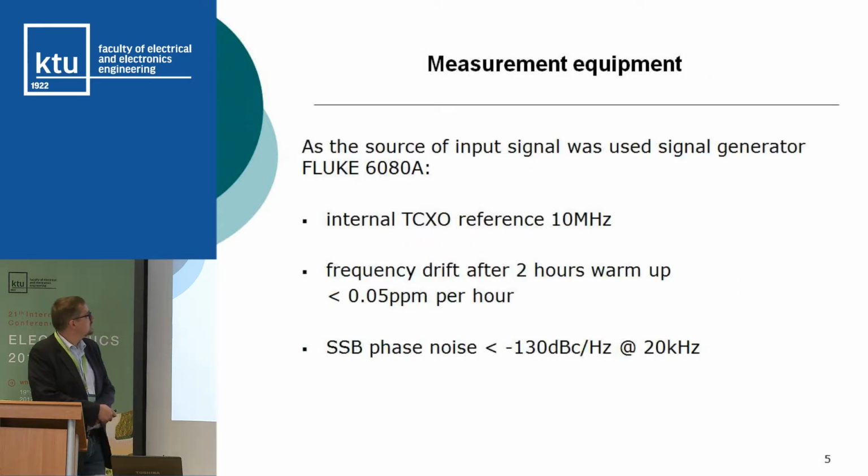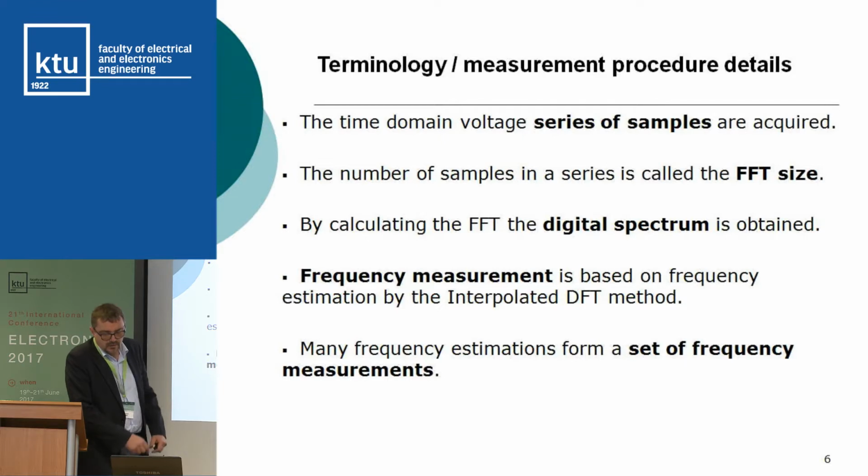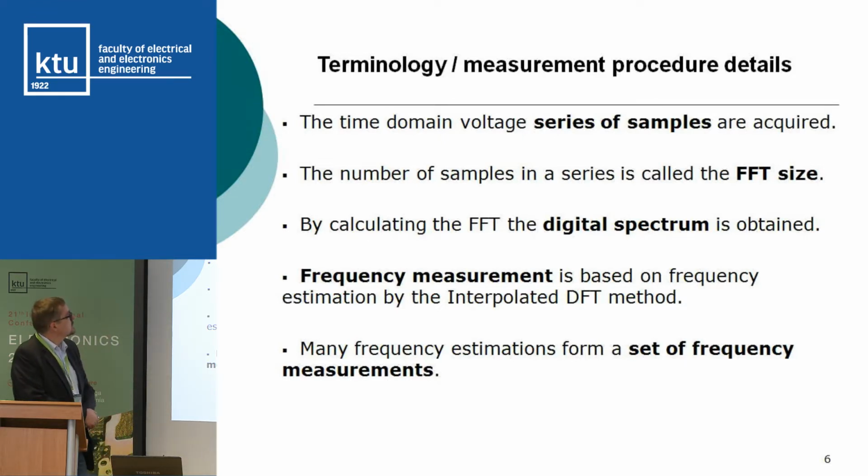To check the properties of the device, we used a Fluke 6080A signal generator, which produces a very stable and spectrally pure signal. The measurement procedure wasn't so simple, so let me introduce some terminology. First, the device acquires a series of samples, a voltage series of samples.